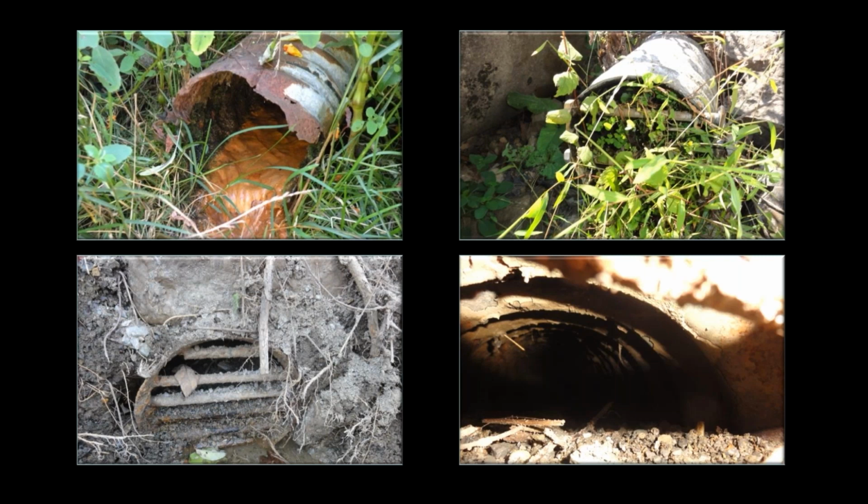Everything we said about the conduits is also true about the drains as well. Those are important features in the dam, and they need to be inspected and maintained as well. Some of the problems that you might encounter with a drain at the toe of the dam that you wouldn't normally encounter with outlet works, though, are precipitates.